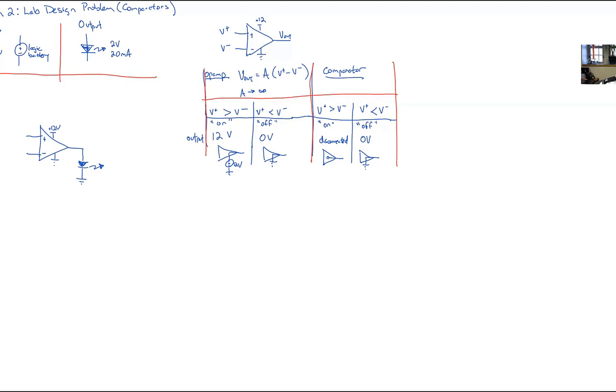So the way we've drawn it, either way, that LED is going to be off. That's not a very useful circuit. We might as well just not hook up the LED at all. And so we can't use it. Instead of tying that LED low, we are going to tie that LED high. The arrow on the LED still has to point down, because it always goes in the direction of current flow.